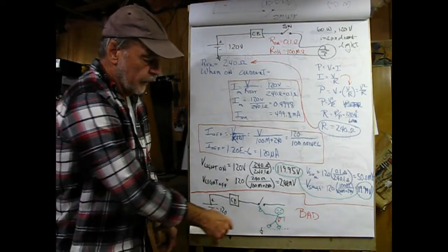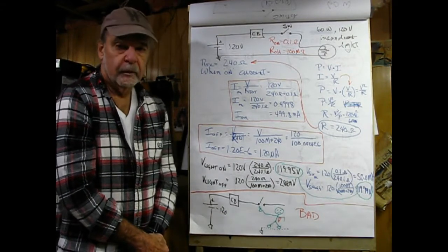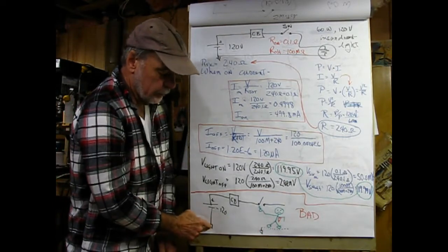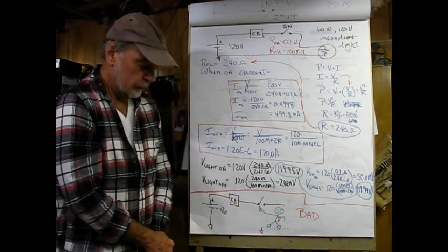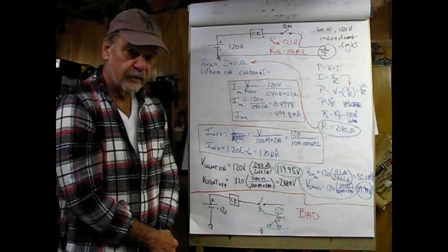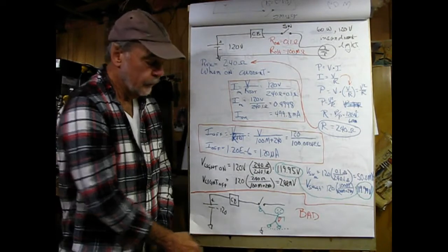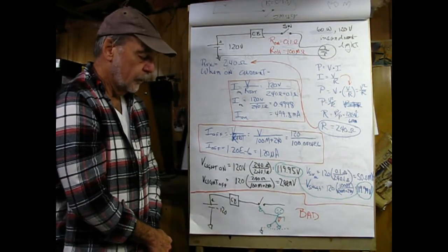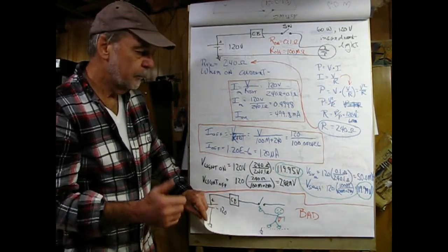Another measure: if I'm outside, say standing on a garage floor, and I don't know what the moisture content of the concrete is, I might have a partial ground, and this is a ground symbol here, back through my body to the voltage source. So once again, outside it's even more dangerous, because all you need is one point of contact on your body, and the other is basically something you're not aware of, which is your feet. So once again, open the circuit breaker, unscrew a fuse, whatever. Be safe.